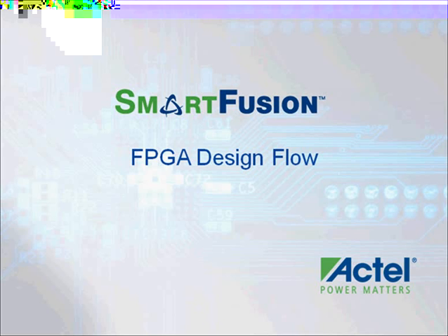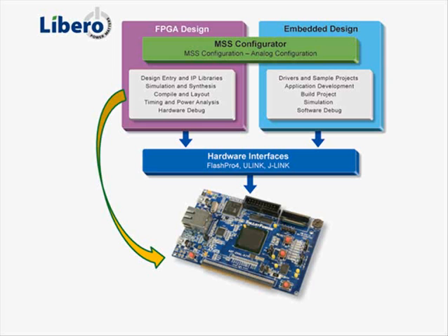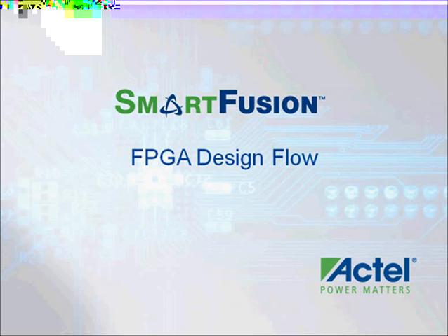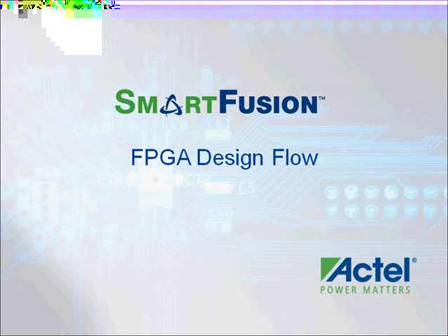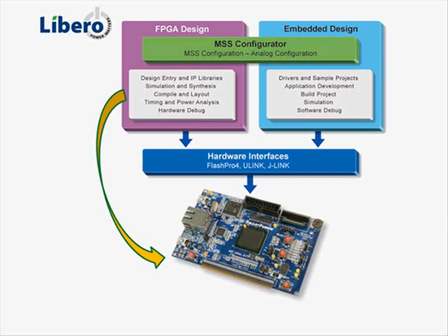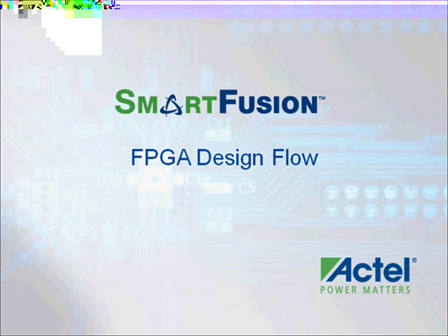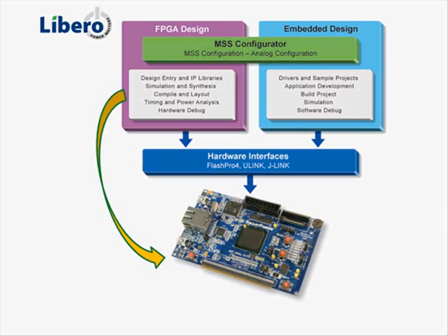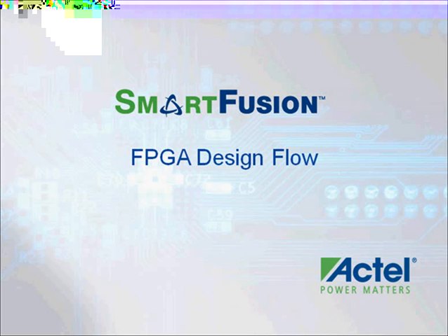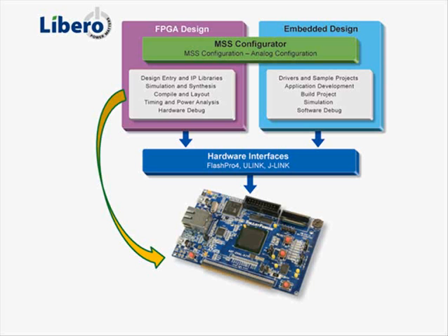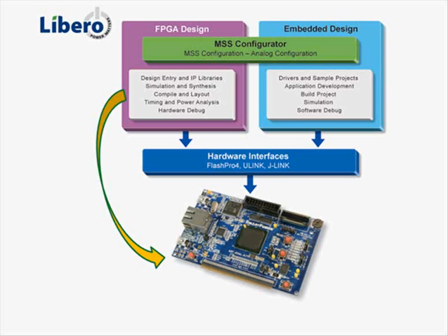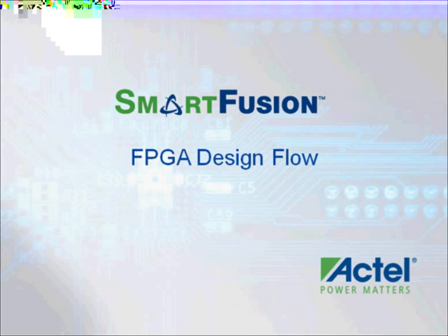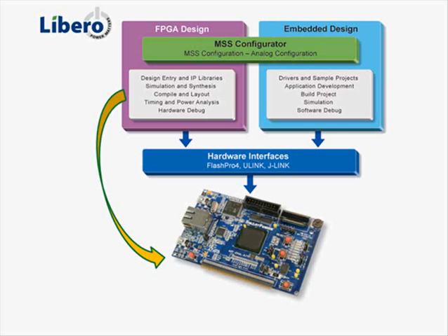the Libero IDE project. Before starting your SmartFusion hardware design in Libero IDE, you should predetermine the IP cores that you will need for the design project and make sure they are downloaded from the Actel web repository into your local PC IP vault, typically located in the Actel Common folder on your C drive. For this project, the local IP folder already has the SmartFusion microcontroller MSS, CoreAPB3 bus interface, CoreAPB SRAM, and CoreUARTapb downloaded and available in the Common folder on the C drive.